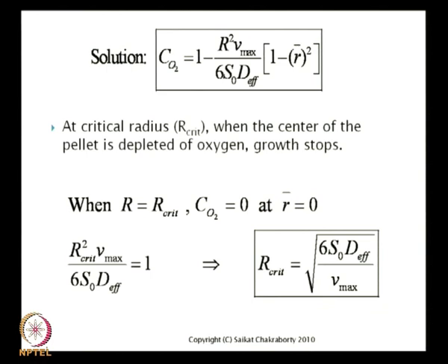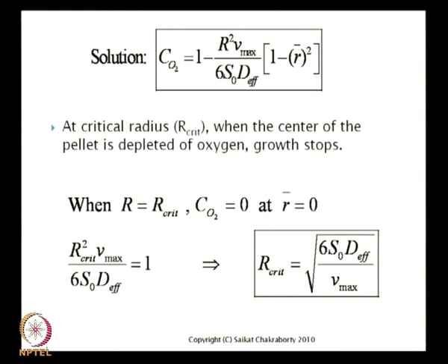Is it clear? So, what we looked at is, we are looking at different things at the same time. First we looked at the normal growth kinetics, and how the kinetics changes, and what is the dynamics of the kinetics, and how different models had been proposed to quantify these dynamics. And what we figured is that of all the kinetic models that have been proposed, it's either the Monod model or the modified Monod model which are the most useful models. Then we looked at the effect of mass transfer, did a couple of examples, and just as we had seen in the case of immobilized enzymes, mass transfer affects kinetics, or in other words decelerates kinetics.